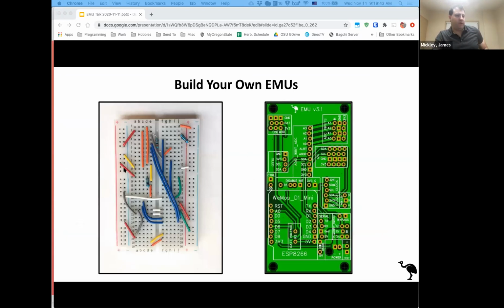And here I can show you, this is a breadboard on the left. The way breadboards work is that all of the rows where it says row 1, that's all connected. So when you plug 2 wires into that, you're basically making an interconnect. You can use that sequence to make a little circuit. And then it's really nice and easy to copy because you can just say, well, put a wire from C2 to C11. And we can actually just write these things down for students to follow the prototype.